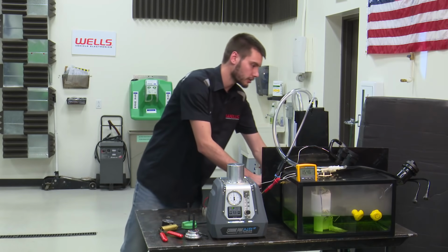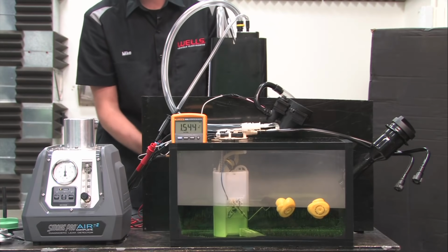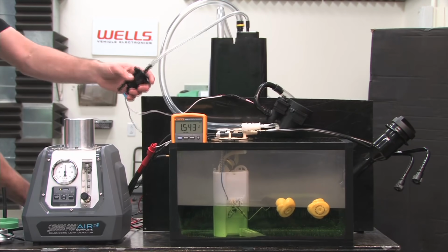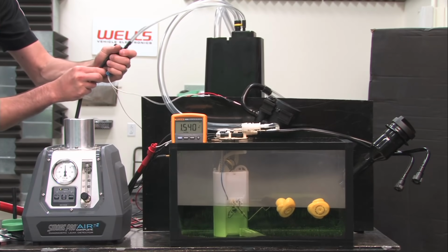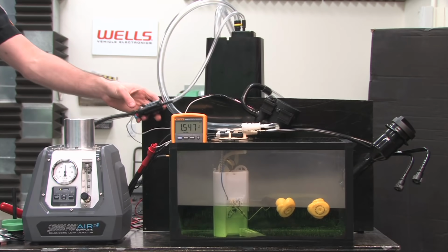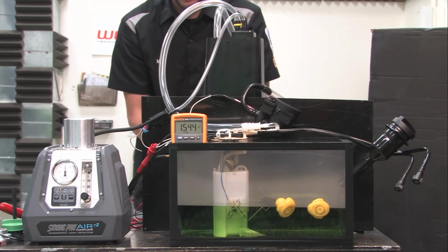I'm going to go ahead and close our vent solenoid. Our vent solenoid is closed. I'm going to close our purge solenoid. So now the front door and the back door are closed. And what I'm going to do is I'm going to go ahead and test this system. I'm going to start with vacuum. So I'm going to put a vacuum pump onto our purge solenoid here. And now I need to reopen this valve in order to draw a vacuum on it. So I'm going to open our purge back up.